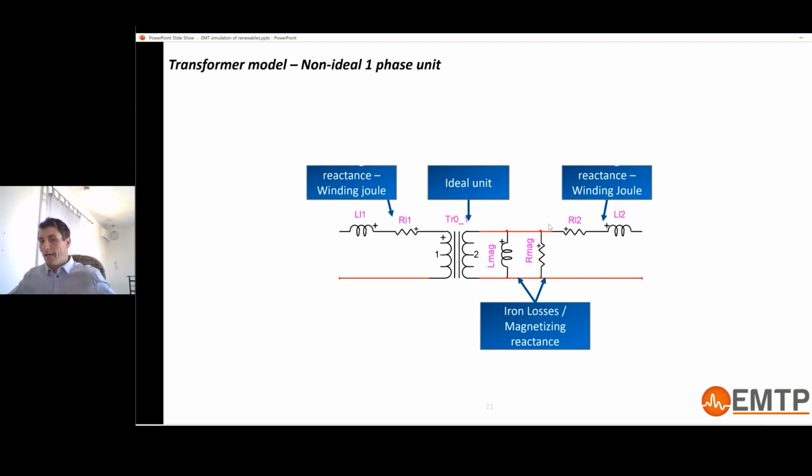But if you are doing a load flow or a short circuit and so on, it does not really matter how the percentage is split. So you can do 50-50 or put 90% at the primary, 10% at the secondary. This is something that is done very often.